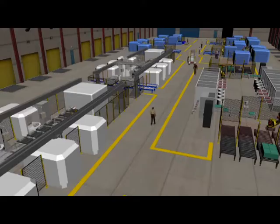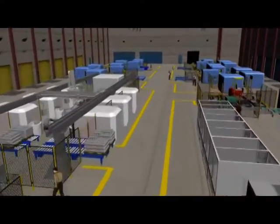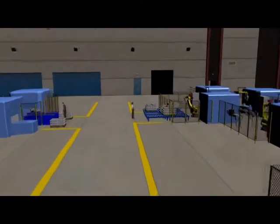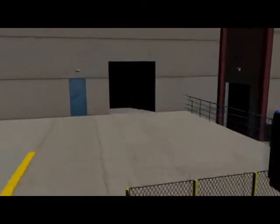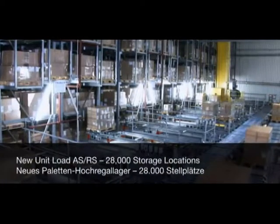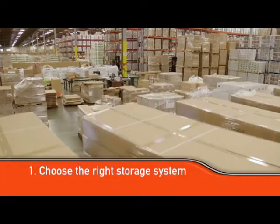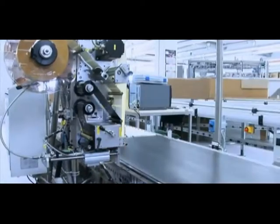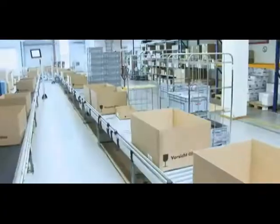Step 11. Select material supporting equipment. The facility planner should use an organized approach in determining equipment needs, following the flow of material from the receipt of material to the warehousing. Generally, there are 6 sections: receiving and shipping, storage, fabrication, assembly and paint, packaging, and warehousing. Material handling devices should be used in as many areas as possible, and everything should work together.